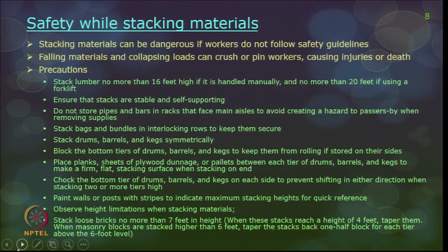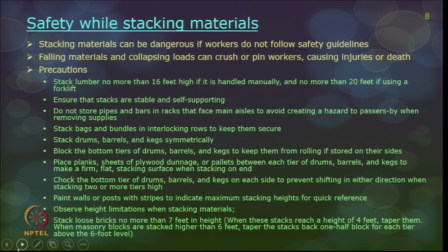Safety while stacking materials. Stacking materials can carry a serious potential for struck-by, falling object, or caught-in-between hazards. It can be dangerous if the workers do not follow safety guidelines. They should know how to stack cement, how to store cement bags, fine aggregates or even bricks on the construction site. If they do not follow the safety norms, then obviously you are going to have hazards. Falling materials and collapsing loads can crush or pin workers, causing injuries or death.